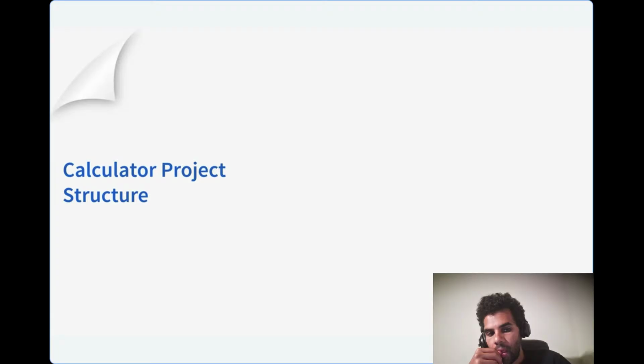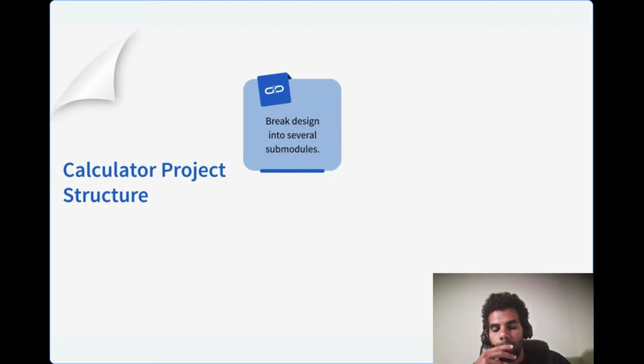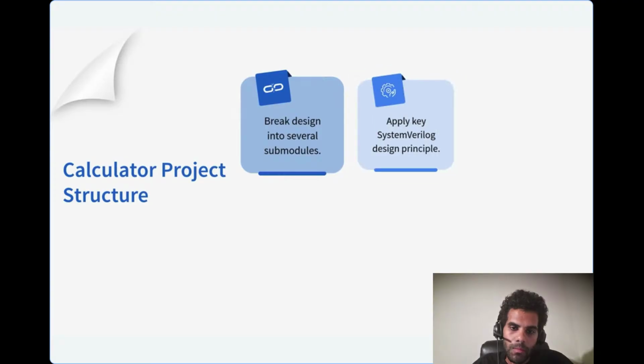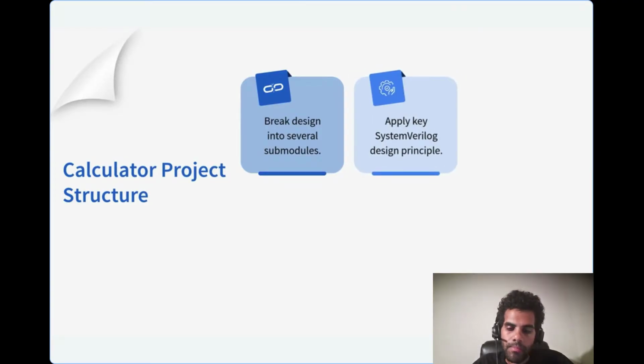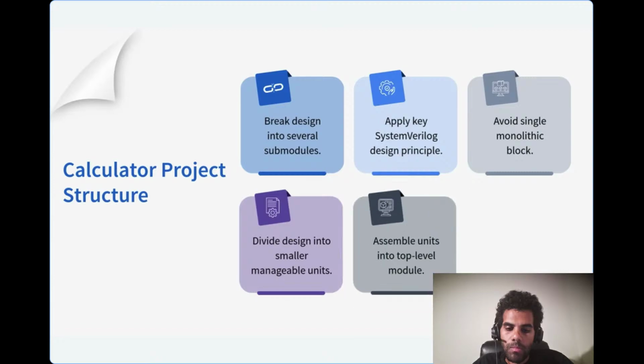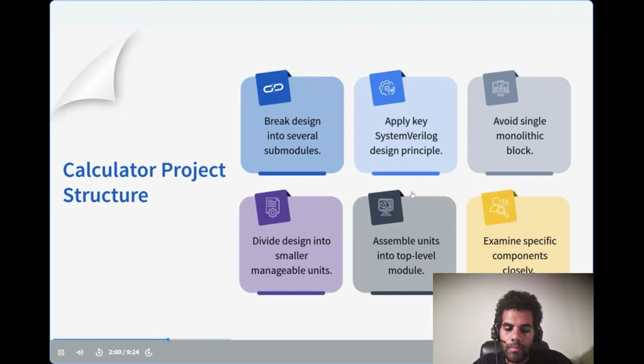So for our calculator project, we are going to break the design into several submodules. This is a key principle in SystemVerilog and in hardware design in general. Instead of building a single monolithic block, we divide the design into smaller manageable units and assemble them into a top-level module.